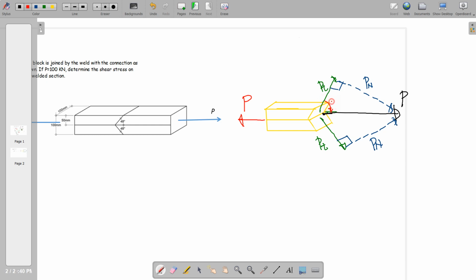Now it is noted that this tangential force is inclined at 48 degrees with the horizontal, and there are two of them, two tangential forces here, which are considered as the shear force on the cut portion, oppositely directed against the tangential component of P. So if this is 100, the resisting force here, since it is shared by these two surfaces, is not 100, we can just have the resisting force here equal to P over 2, or 50.